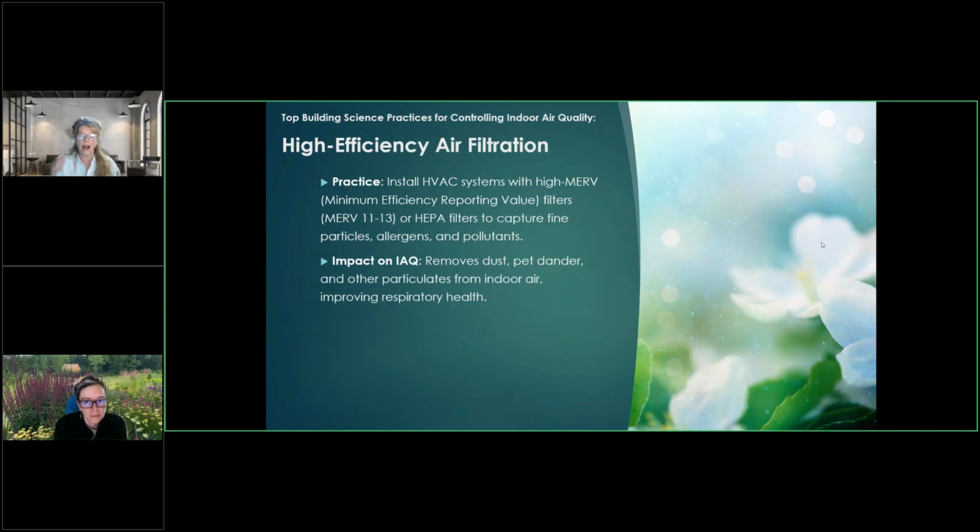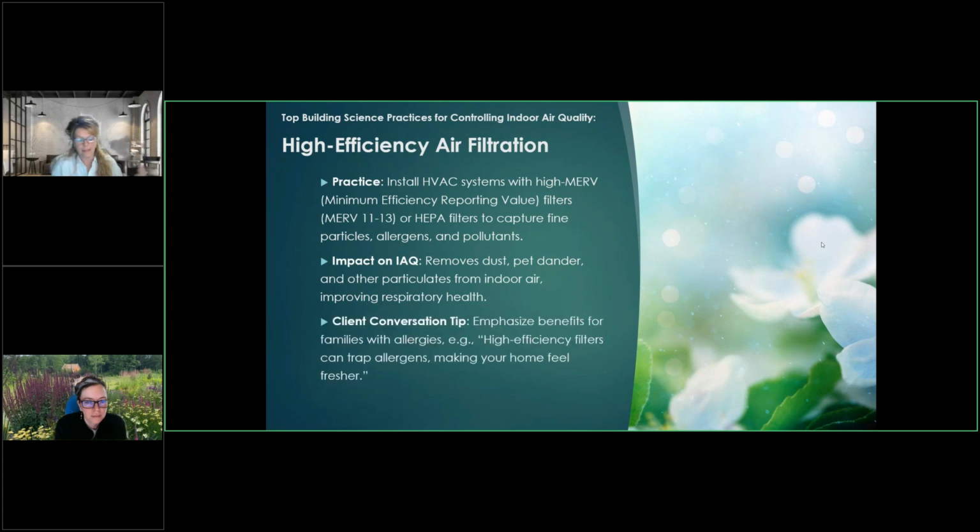I always tell people that when they're vacuuming, make sure the system is on, because whatever you're stirring up, hopefully it's making its way to that filter. But again, it's only going to collect what is making its way into the ductwork. There are a lot of great filters out there, and there are a lot of proven benefits to having high efficiency filters.